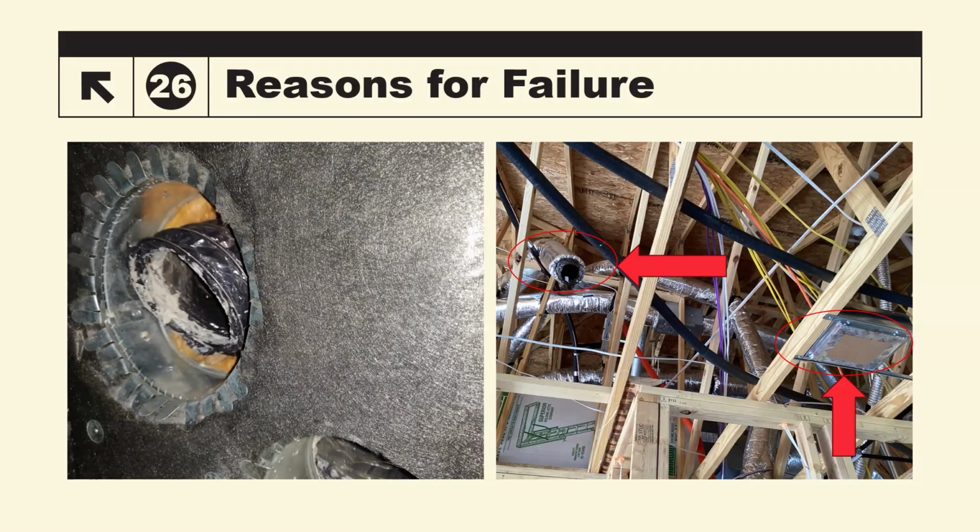And of course, most third parties won't go to the extreme of looking for this. You're just assuming they did the right thing. And then if you looked inside the plenum and you try to get a camera in there to see it, then you find things like this. That's not really ever going to pass unless it's done correctly. I don't care how well they sealed it from the outside. If air is allowed to leak through the insulation on the jacket, you've got a much higher test result.